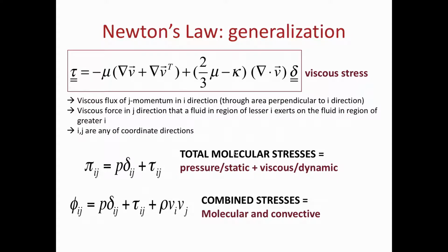So basically our viscous stress has that cryptic formulation, but that basically describes a Newtonian fluid. I have the Jacobian of my velocity, which is a tensor. So gradient of a vector is a tensor. Gradient of a scalar function is a vector. So go up in dimensionality. And then I have a constant times divergence. Divergence of a vector is a scalar.